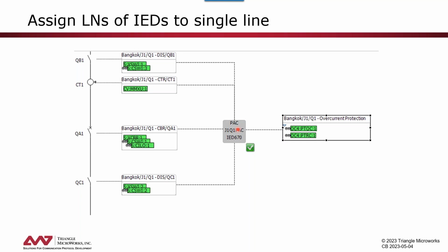Now we can link them to the IED, and as such, we know now which instance of an IED, which logical node within that IED is exactly doing, as an example, the interface to this disconnecting switch, which one is doing the control, so we can directly associate what is implemented in a device with where this functionality is located in our one-line diagram.